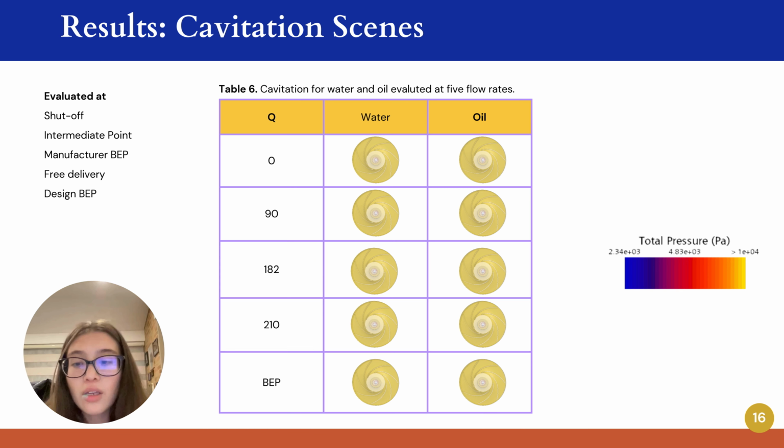The cavitation profile was performed. This phenomenon occurs when the fluid pressure is lower than the vapor pressure of the fluid, causing bubbles, which is indicated in our different cases for the pump since the yellow color is in most parts of the pump. It is expected for future occasions to focus more on geometry since this influences the pressure distribution and speed of a fluid. If it is not designed properly, these low pressure zones can occur.